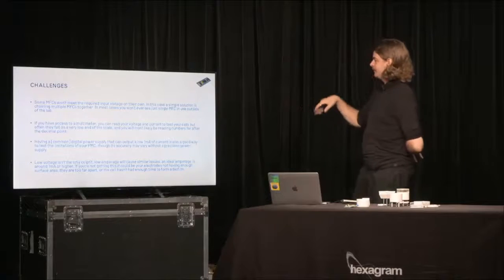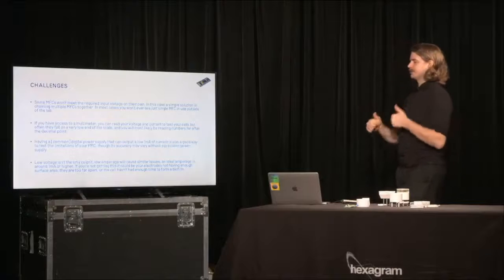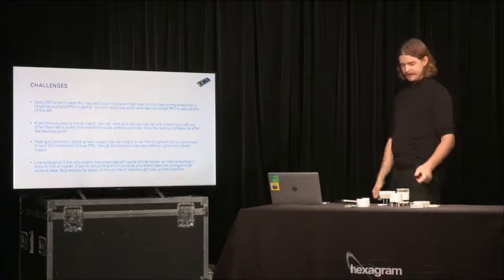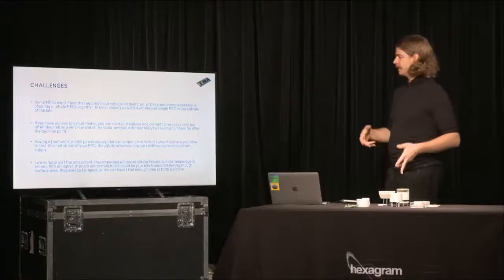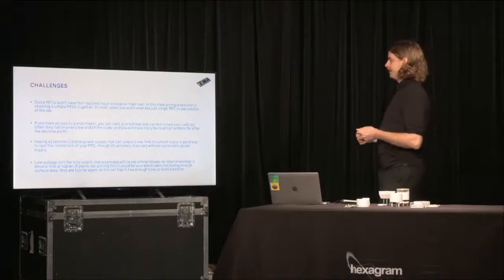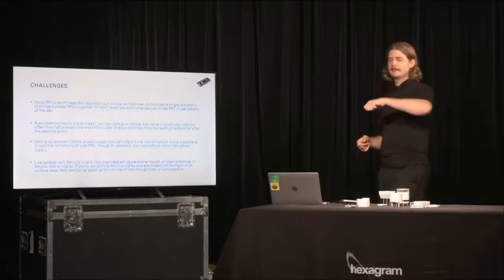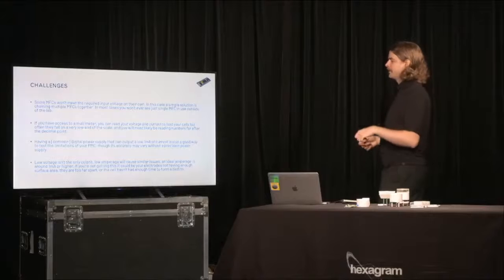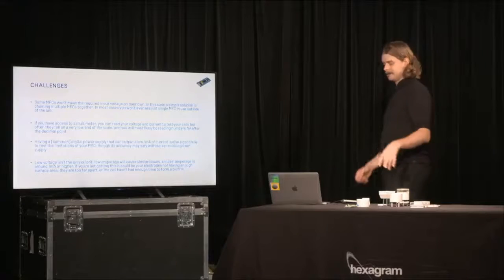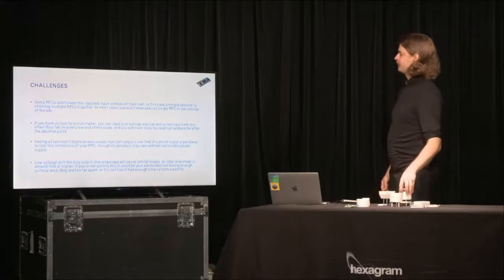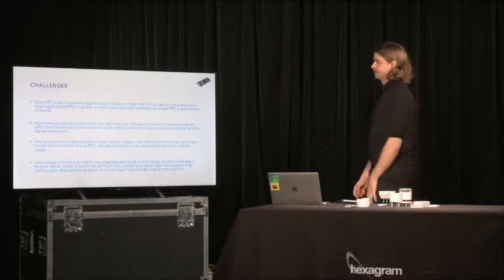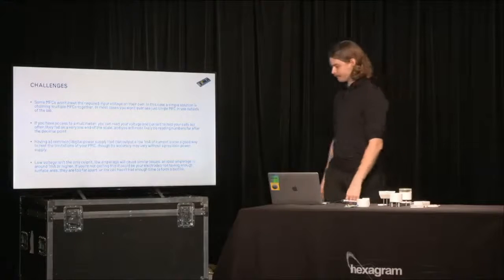You want to check on a multimeter probably how much voltage you're getting, so you can test as the cell's growing how much is there. You need to put it basically on the lowest setting to be able to get anything, and even then it's probably going to be in the decimal points. To actually get a really good reading, you need specific equipment, but you can do it with a hobbyist multimeter and power supply.